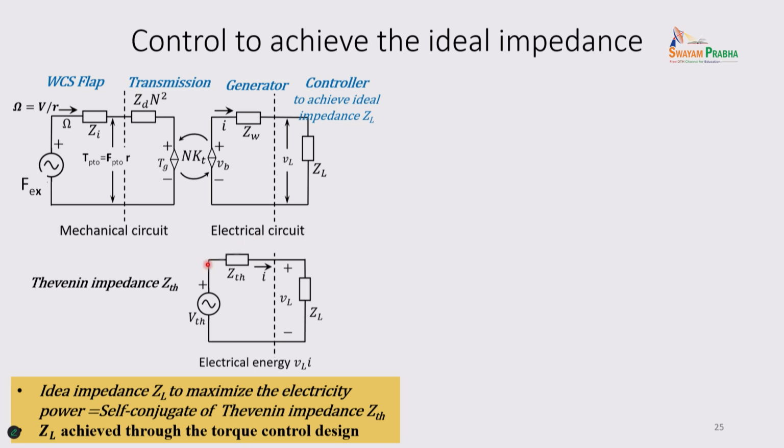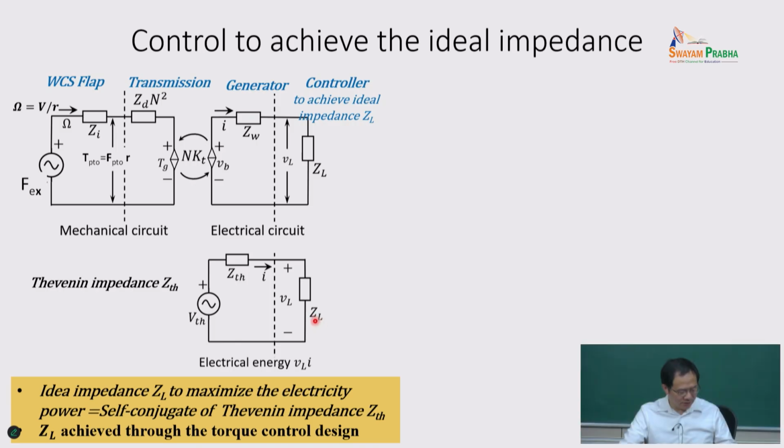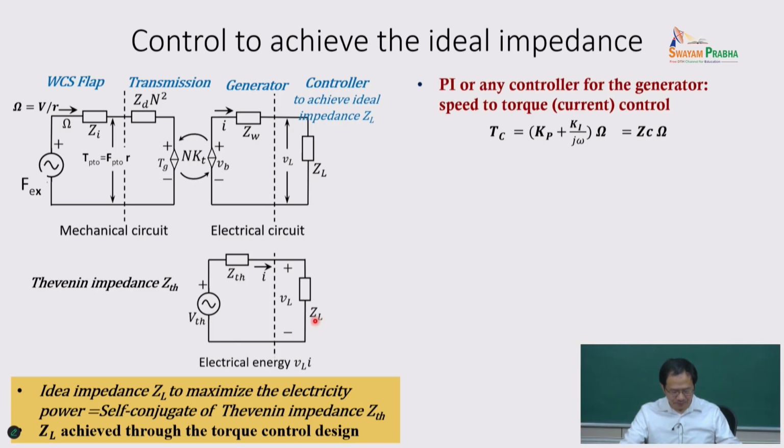If this voltage is constant and you consider this impedance a resistor, you match the two resistors. Now, if you use AC voltage, there's a real part and an imaginary part, then when you want to maximize, you have the complex conjugate, right? We highlight again and again, have the complex conjugate, okay.